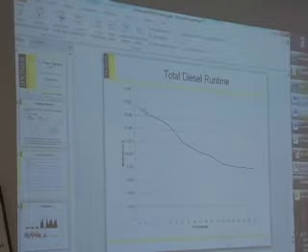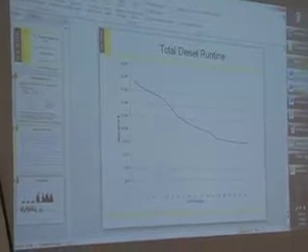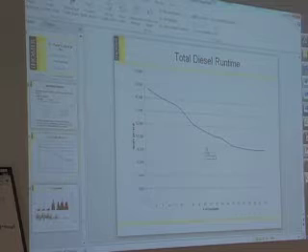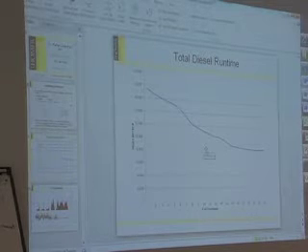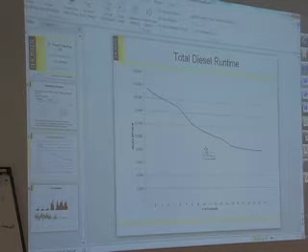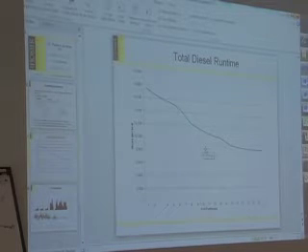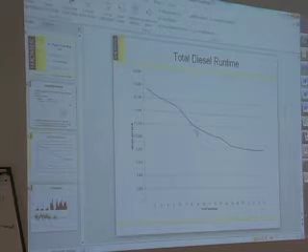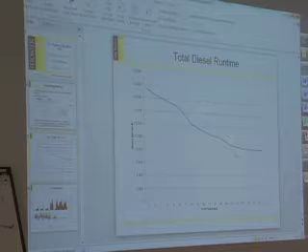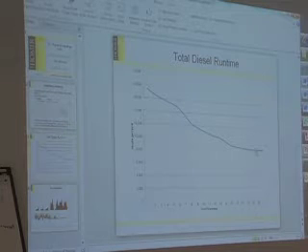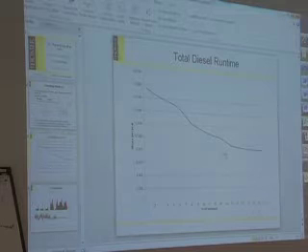Well, as you add more flywheels, you can start shutting down the diesels, because the diesels are being used to a large extent just for spinning reserve. And the flywheel can provide that spinning reserve, so you can shut down the diesels. And although it's not a nice smooth curve, you do reach a point of diminishing returns. And so their optimum is in here somewhere.